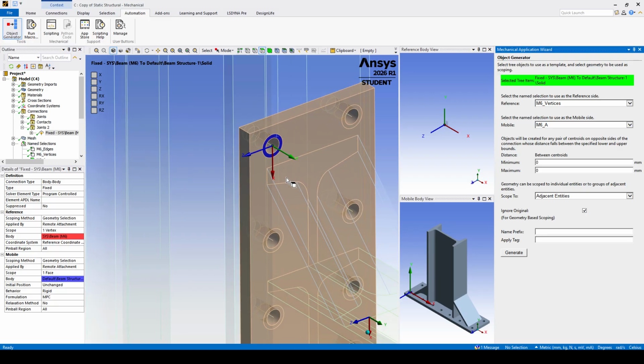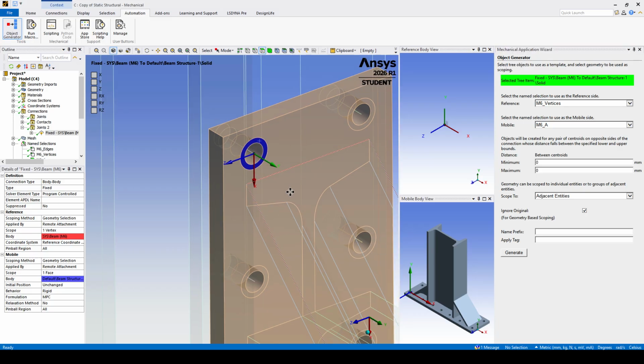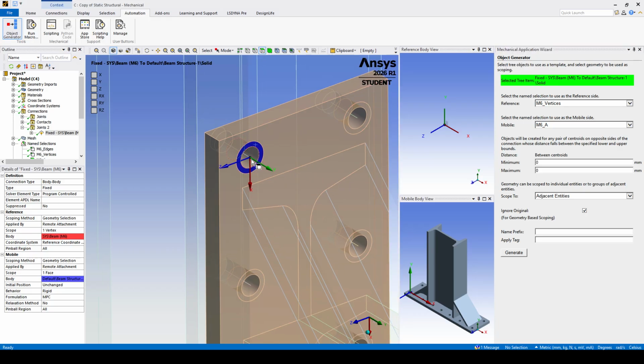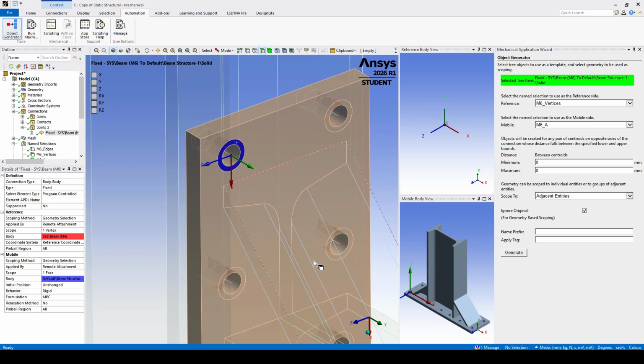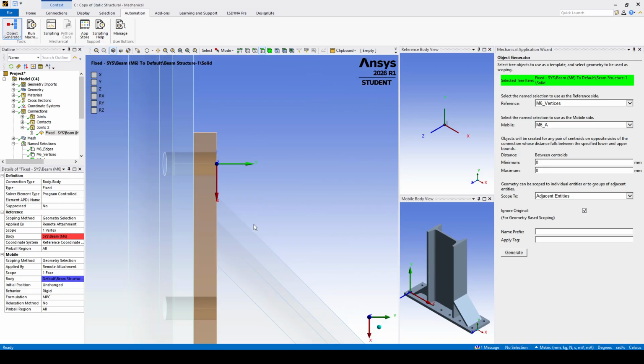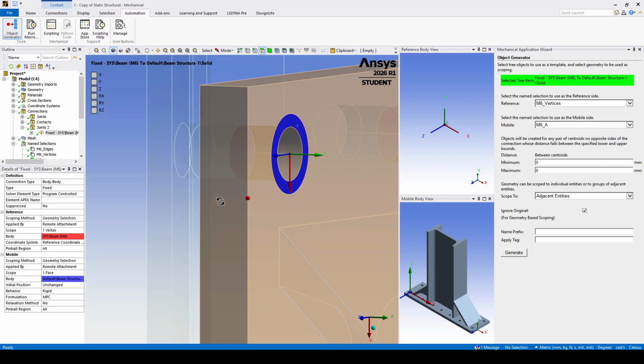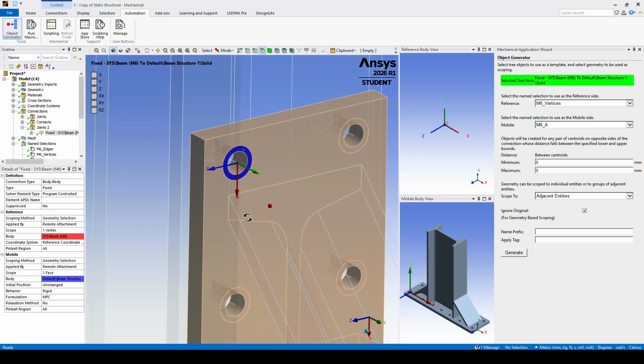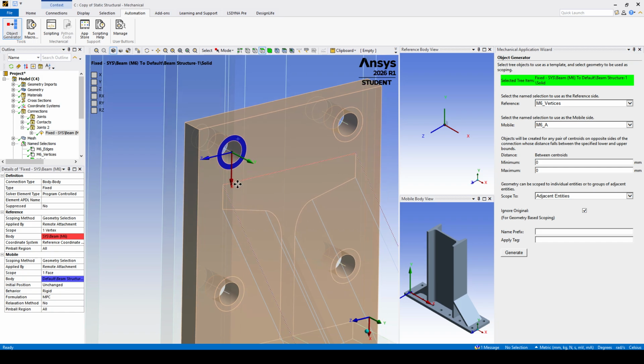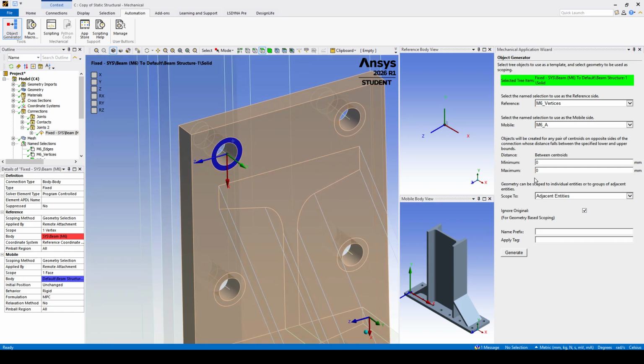In my case, this distance is the distance from the vertices to the plane of this face, which if we look from the Z direction, is on the same plane, which is 0. But to make sure that all joints will be generated correctly, I recommend you put 1 on the maximum cell there. So we put 1 there.